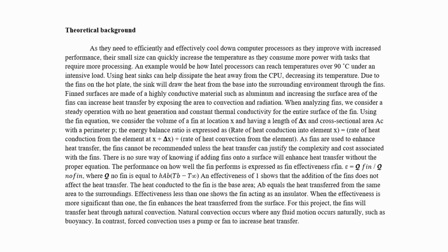As fins are used to enhance heat transfer, the fins cannot be recommended unless the heat transfer can justify the complexity and cost associated with the fins. There is no sure way of knowing if adding fins to the surface will enhance heat transfer without the proper equation, but how well the fin performs is expressed with the fin effectiveness, epsilon fin, equation: epsilon equals Q fin divided by Q no fin, where Q no fin is equal to h A_b (T_b minus T infinity). Effectiveness shows how the addition of the fins affects the heat transfer.